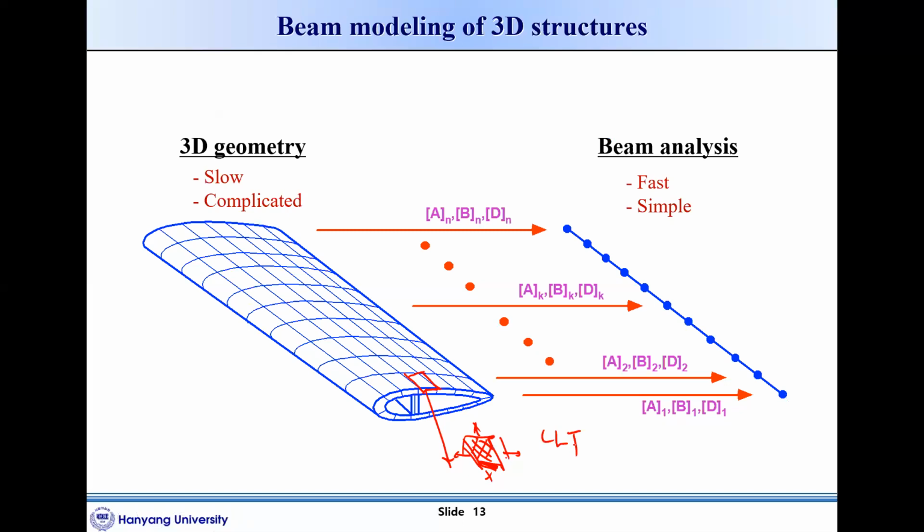Okay, so the theory applied to that element is already understood. And the good thing is that we have many different angles. I mean, the layup sequence can vary all over this section, all over this way. So what this tool does is combine all the layups and information and construct this section's bending stiffness. This one would have its own bending stiffness, right? And torsion stiffness. And that's basically what it does.